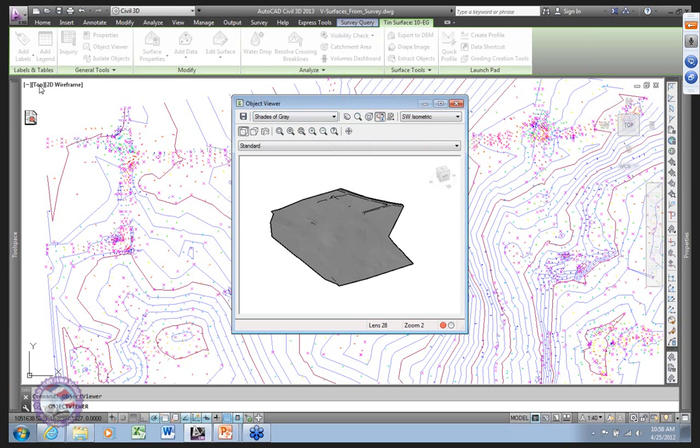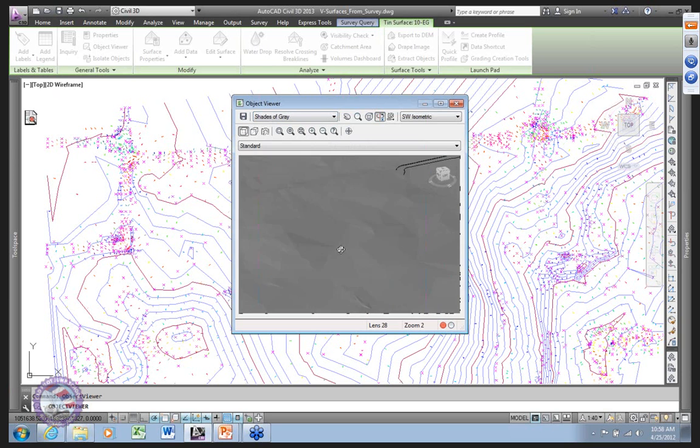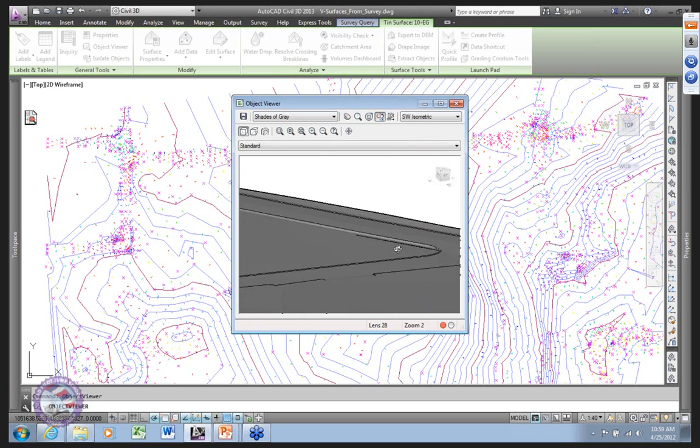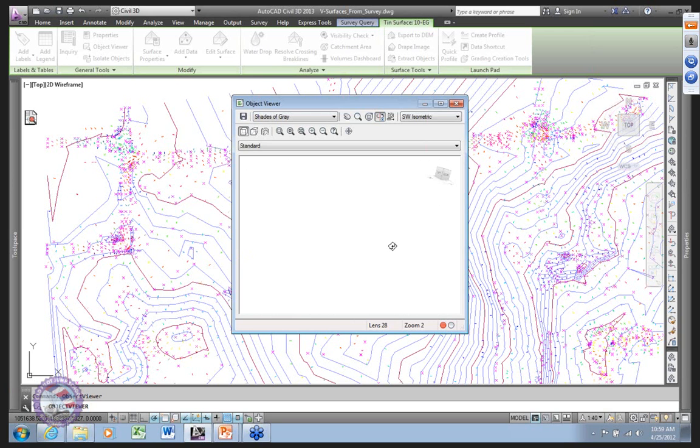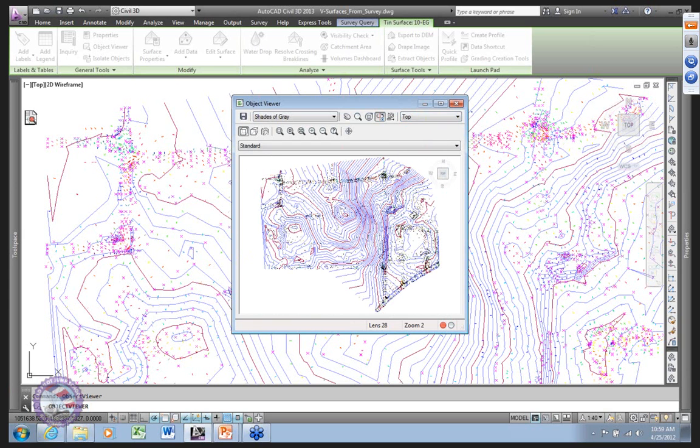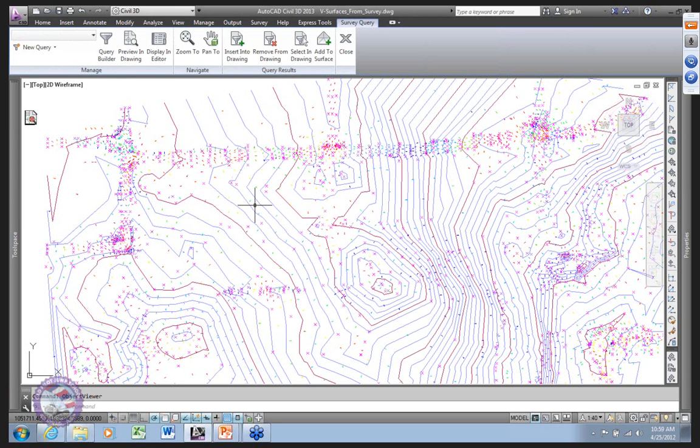You can actually do this in 13. Don't do this in 11 or 12. You can do this without as many regions and with better video performance with the same hardware than before. So you can actually kind of visualize whether those little break lines and ditches that we're talking about, are they really happening, right? If you get lost, you can go back to where you were, okay? And so this combination of visual style, graphic style, right? AutoCAD graphic style, right? Visual style is a really handy thing to have.